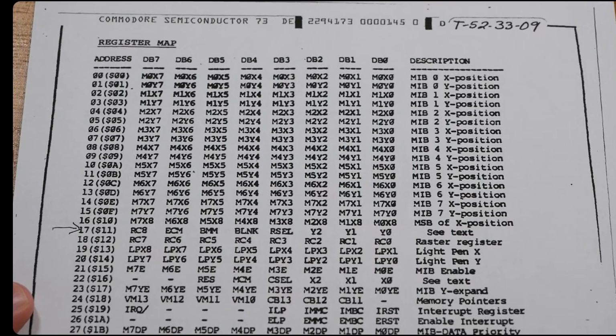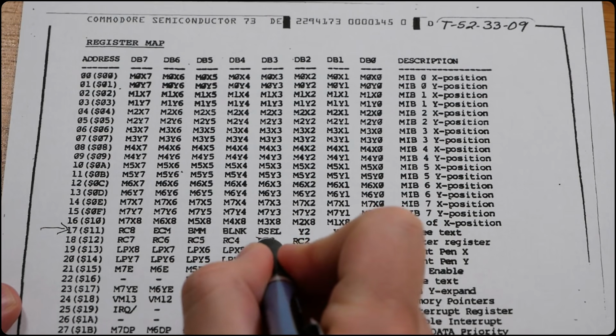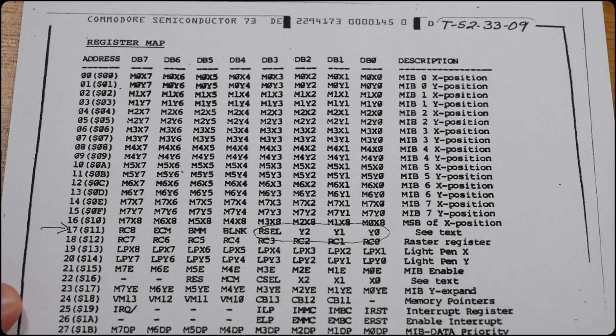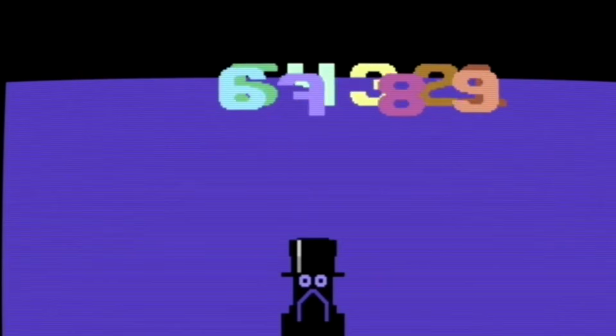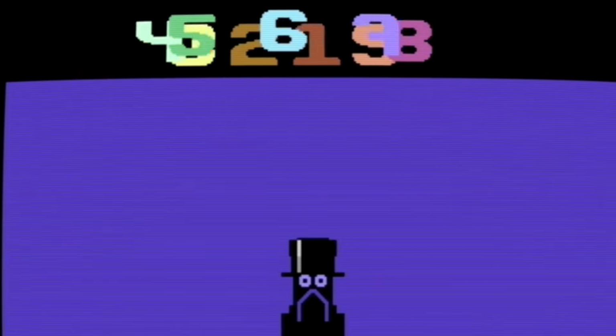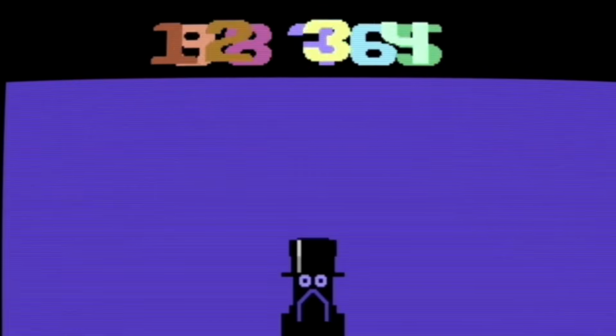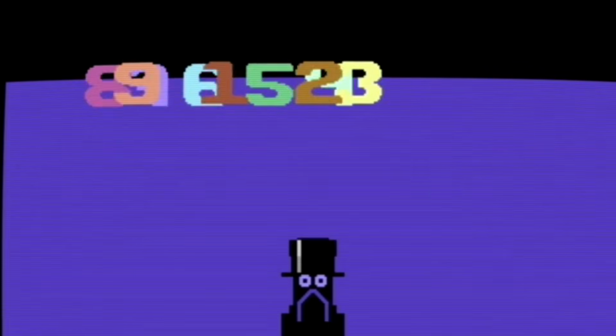There is one thing left to clarify. As I mentioned, this trick relies on the lower 4 bits of D011 being ignored in the border area. But in the demo, the device moves seamlessly between the border and the text area. How does that work? And the answer is again that just as in a magic performance, what looks like a single effect can be produced in several different ways.